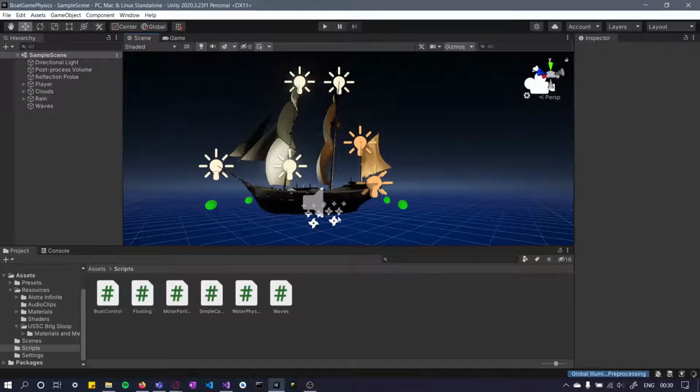So this asset is a boat. For anything that needs to float on water, the main thing which we need to handle is the volume of that object. So volume is what makes and breaks the buoyancy force required for that object to float. If we know the formula of buoyancy, it is F is equal to rho V g, where rho and g are basically constants in a scenario. So rho depends on the water and the waves. That can be something that is treated as constant in a scene, which is simulated like this. G is obviously a gravitational constant that can also be treated as a constant.